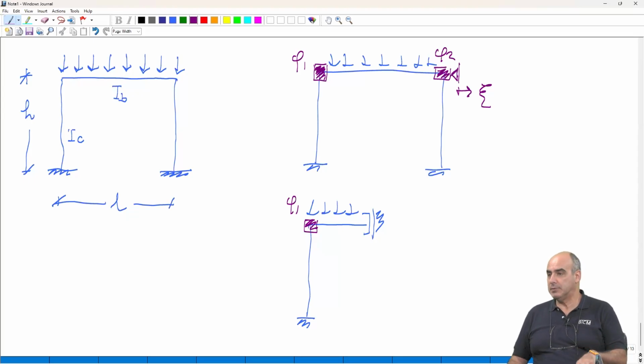But in real structural analysis, what your software does is solve a system of n equations in n unknowns. And the computational time goes with the square of the number of unknowns. Well, computational time is now cheap. But also consider that the way in which you numerically solve a linear system of n equations in n unknowns is with forward and backward substitution. You don't go with determinant matrices and so on.